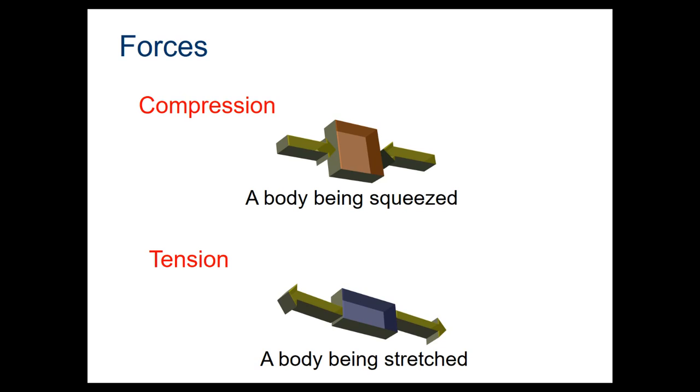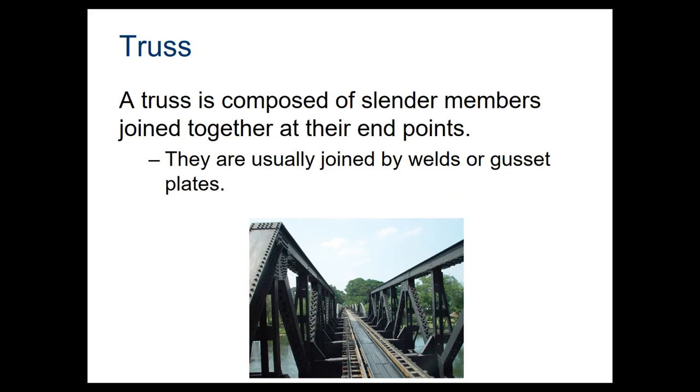And then tension force, as the name implies, and as you can kind of see in the picture, is going to be one that's pulling on the ends. So things like rope and chain or any kind of cabling, we can put those things into tension, and they work very well under tension. They don't work at all in compression, because once you push on them from the ends, they'll just collapse. But as a tension carrying device, they work really well. So ropes and cables and chains, you see those in bridges quite often, especially suspension bridges, where they are supporting a tension load, but they will not be under compression. And so, again, you've got to understand what type of force you're looking at, so you know which type of material to use.